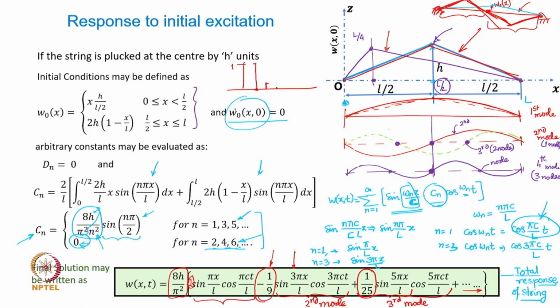So this is how, even in a 2 degree of freedom system, you have seen that if the two masses are initially moved together in one direction in the same amplitude and then released, it will continue to vibrate in the first mode only. If you stretch it in the opposite direction so that the mode shape is 1, minus 1, and then you release it, then the whole motion is going to be only in the second mode, and the first mode will not contribute.